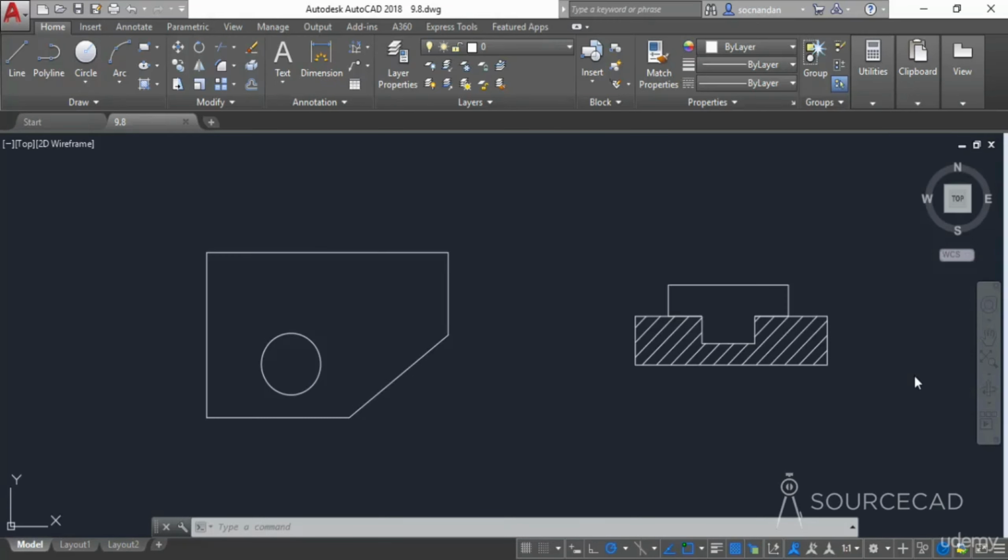In this video, I will tell you about adding feature control frame in our AutoCAD drawings, and the feature control frames are added for representing tolerances and most of the geometric dimensioning and tolerancing information. So in order to add the feature control frame containing all of the GD&T symbols, you need to once again go to the Annotate tab.